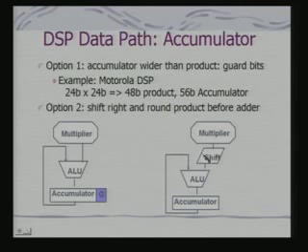Whatever algorithms I have talked about for rounding get implemented in this block, because the multiplier is producing the output, that gets appropriately rounded, and then through the ALU it is added and the result is stored in the accumulator for the multiply and accumulate sequence. So these are the two basic organizations taking into account the precision and the rounding in picture.